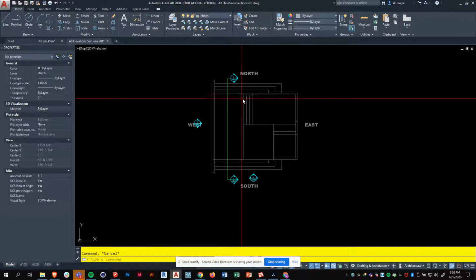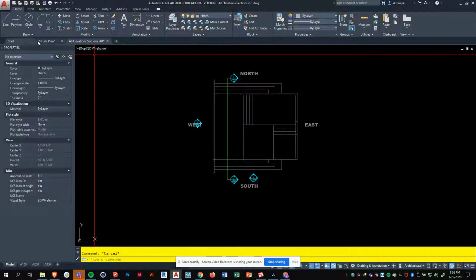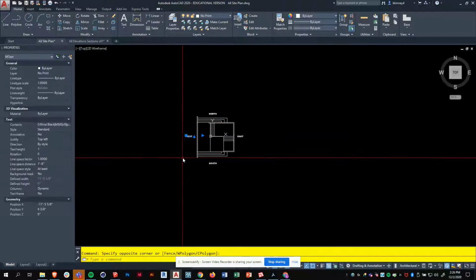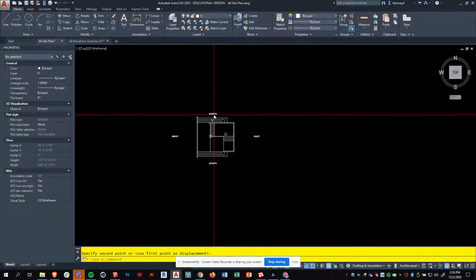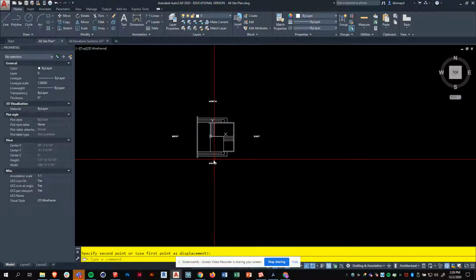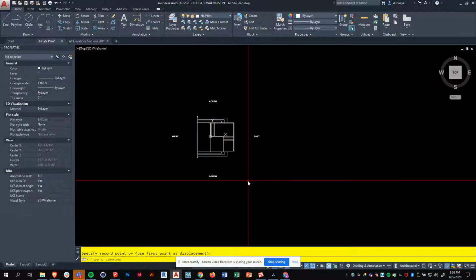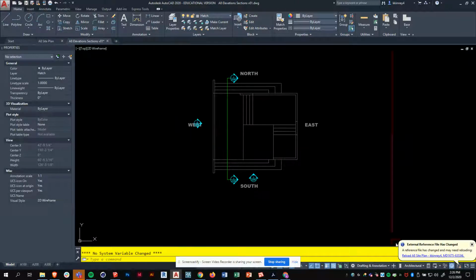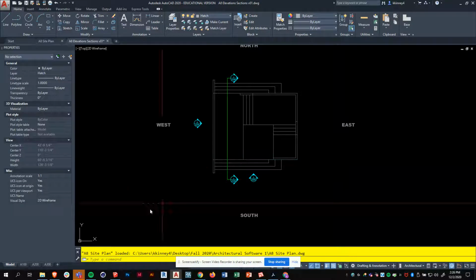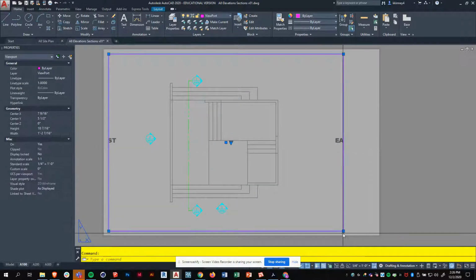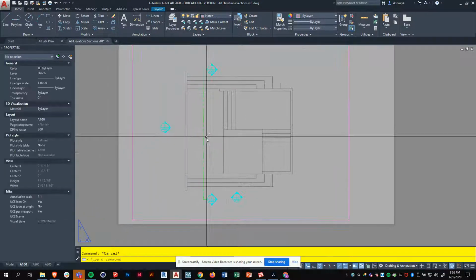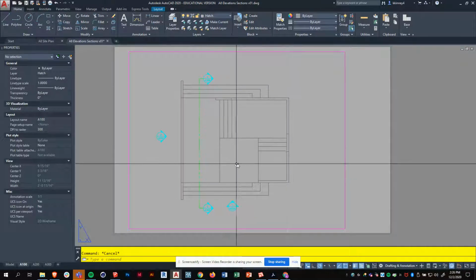There we go. And now, just for clarity, I'm going to go back to that site plan, and I'm just going to move these over because these are just to help. They're not meant to print. Okay, move that up. Okay, I'm going to hit save. Come back over to my elevation sections page, reload it. They're out of the way. And now if I go to my A100, I can move my viewport in a little bit just to not see those. Remember, your viewport won't print either, but the contents will.